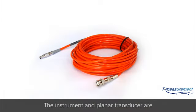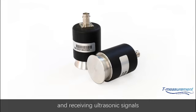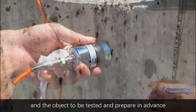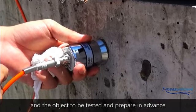The instruments and planar transducers are connected by signal wires. The planar transducers have both the functions of transmitting and receiving ultrasonic signals, so there is no need to distinguish them when using. Coupling agent is required between the transducer and the object to be tested, and should be prepared in advance.